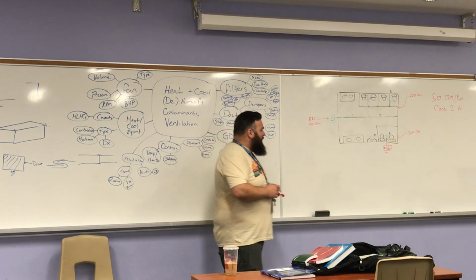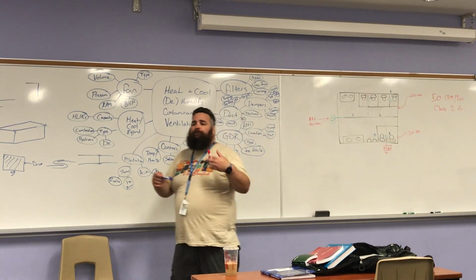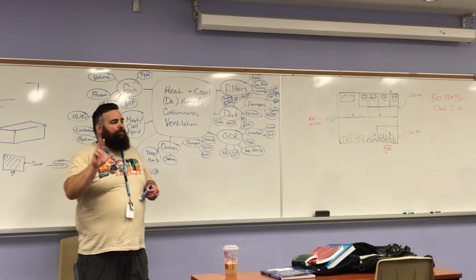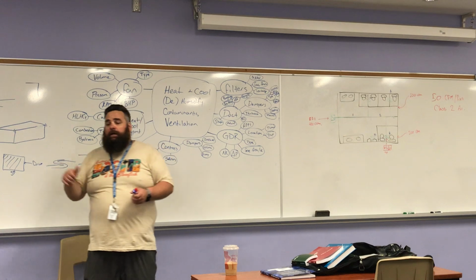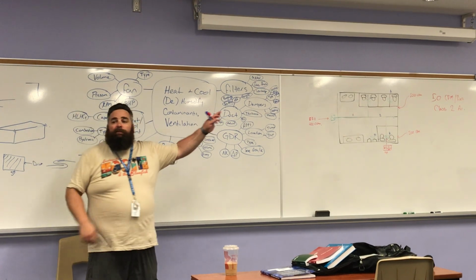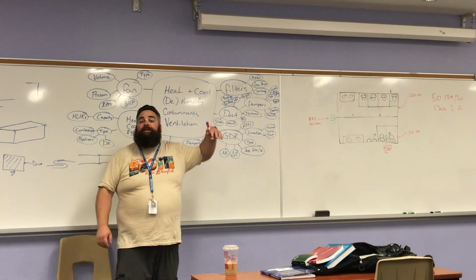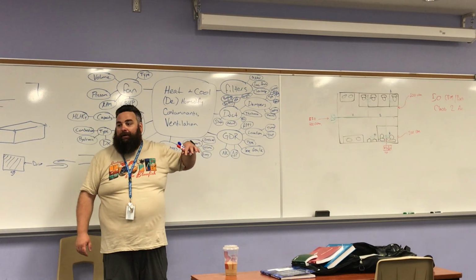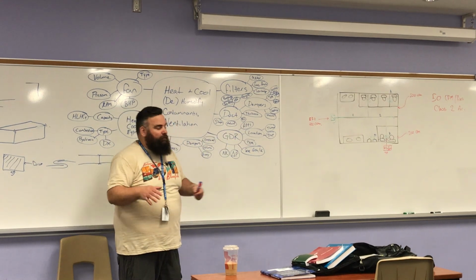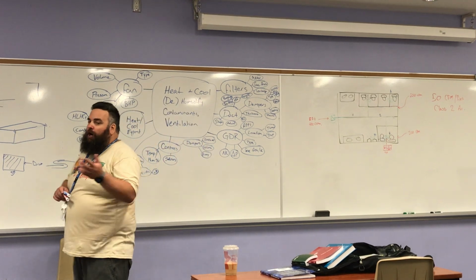What we're going to be doing is sizing this duct according to the equal friction method. There are 3 types of duct sizing. Equal friction method, where we size everything so it pretty much has the same pressure drop, and that way no route is favored over the other. They're all pretty much the same length as far as the air is concerned. Static regain, which we're not going to get into.